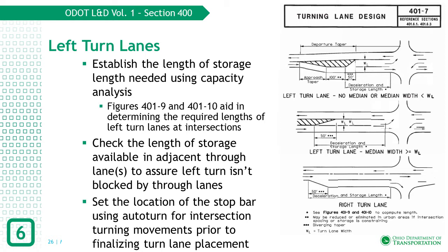Figures 401-9 and 401-10 are to be used to calculate the storage length, which is the number of vehicles that are expected to get through a single traffic signal cycle based on the traffic volume using the left turn lane and the number of traffic signal cycles per hour.